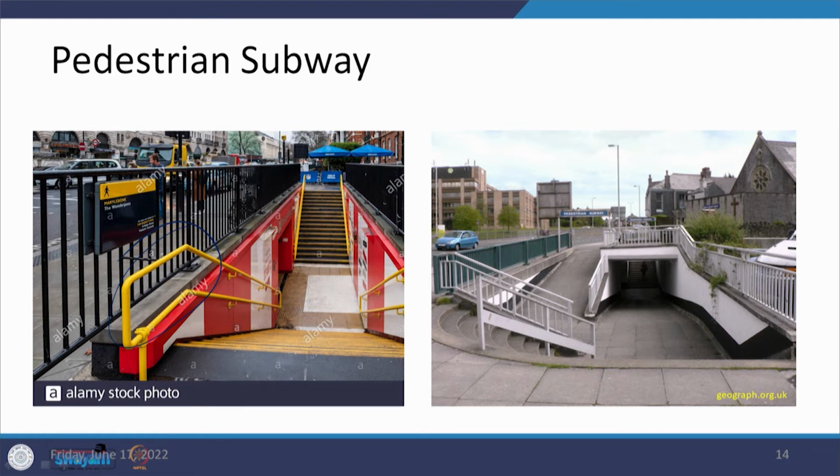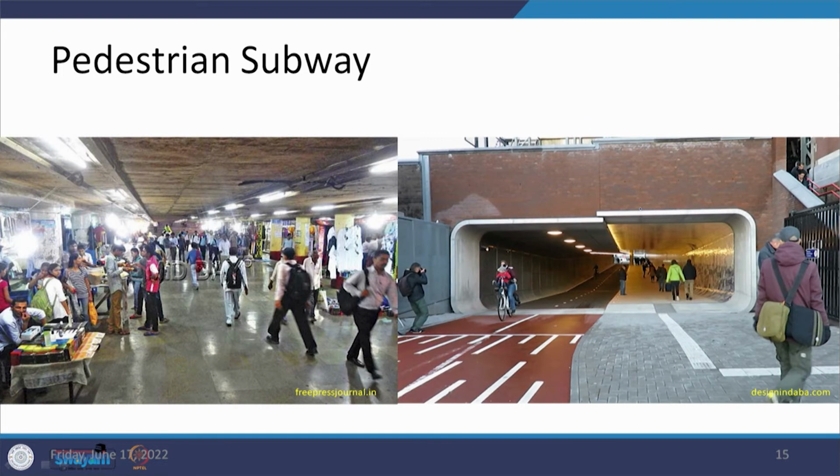Okay. So, this is another thing which can be taken care of, and then one single flight has been provided on either side, because not many people are there, but it is also going to depend on the spaces which are available. Here in this case we can see the ramp is also provided on two sides, and the stairs are provided on this side with railings on either side, so that the person can hold and go down, and then the ramp takes the person towards this and it comes up from the other side. Here this is a hawker zone which is provided.